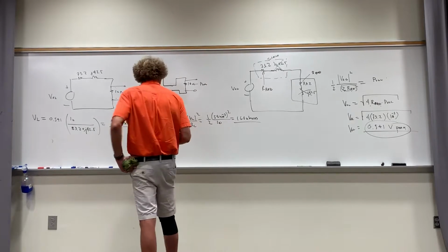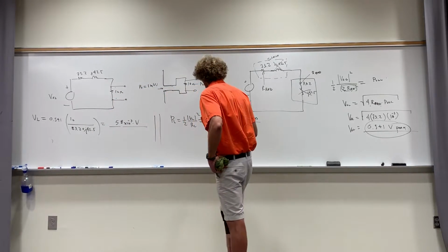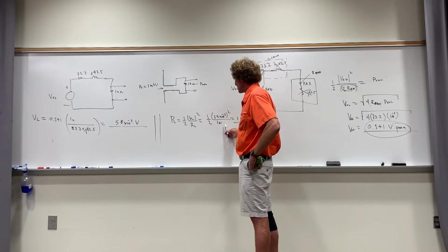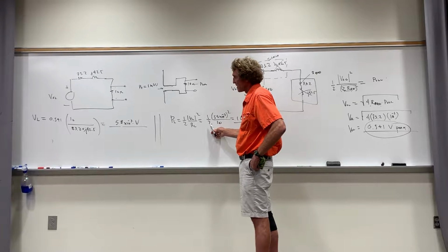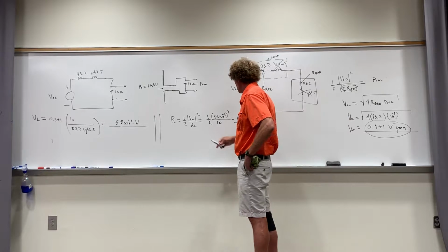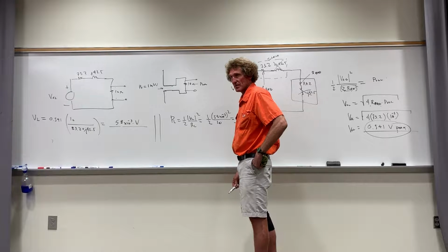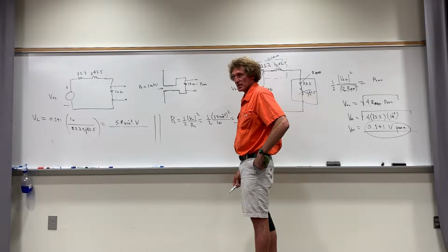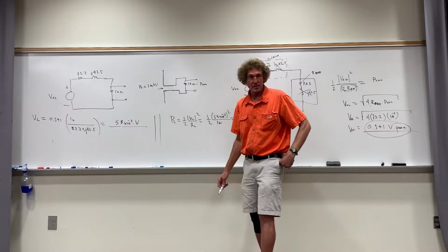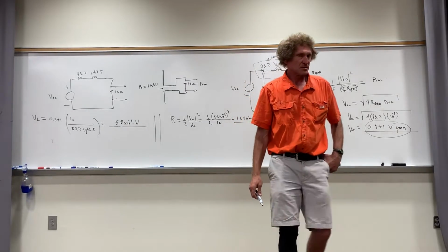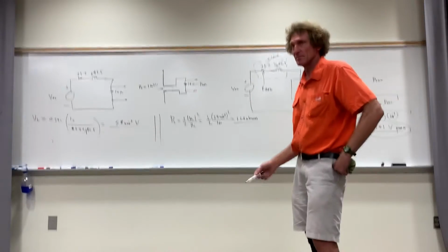Right. So if we take that voltage and square it, and divide it by the resistance, which is 10, and then by 1/2, because in fact that's not an RMS voltage, that's a peak voltage, that should be the right answer. If he has twice that value, there's an anomaly. There's nothing else in that problem? It's extremely strange, because I've done these problems.